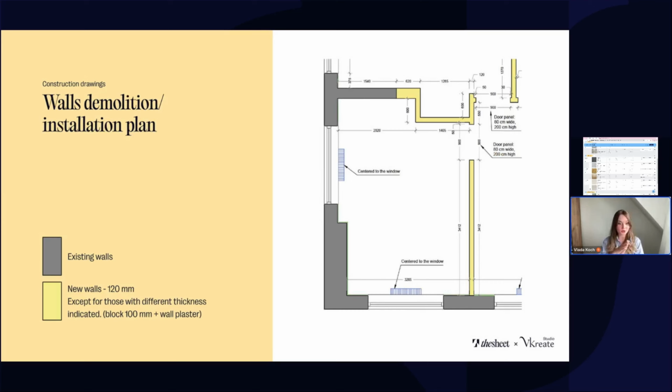And then let's go and start the actual construction drawings, after we do those 2 initial planning and floor layout plans in the design phase. And here we start firstly with the walls. If you have old walls, you have to show the demolition of the walls. And of course, you need to have the new walls very clearly determined on your drawings, and the client and the builders have to see directly which are the existing walls and where you have the new walls.